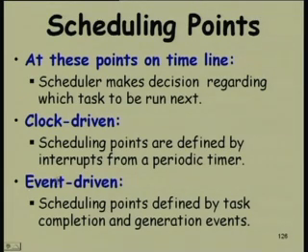On the other hand, we will have another category of schedulers, where the scheduling points are defined by some events which are not really clock events. Here, let us say a high temperature is sensed, or a fire condition is sensed. So, the events need not occur according to some clock, and once the event occurs, a task needs to be released. At that time, the scheduler wakes up and tries to find out what to do, which task to take up, and also when a task completes, the scheduler also wakes up.